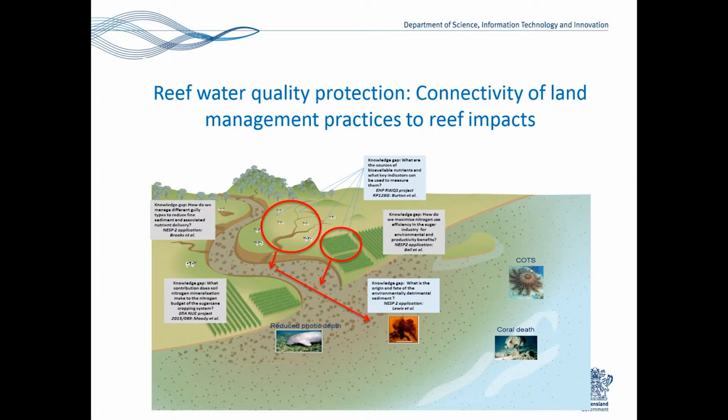There's some good evidence to suggest that while some of the heavier sediments, maybe greater than 63 microns for instance, get deposited close into shore, the very fine clay sediment, maybe less than 10 microns, gets into the reef system and can be transported very long distances and may be contributing to the COTS outbreaks that we have, because there's this thing that's called marine snow.